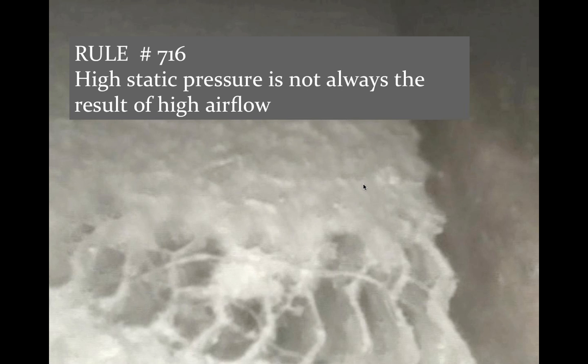This was a PSC motor, and it caused a fairly high pressure reading. You could look at the manufacturer's chart and say, well, high pressure reading, you're getting a lot of airflow or a little bit of airflow, and it may not necessarily be true. It could be due to contamination and not necessarily to the system itself. So you do have to be careful and knowledgeable of what's happening when you take these external static pressure tests.